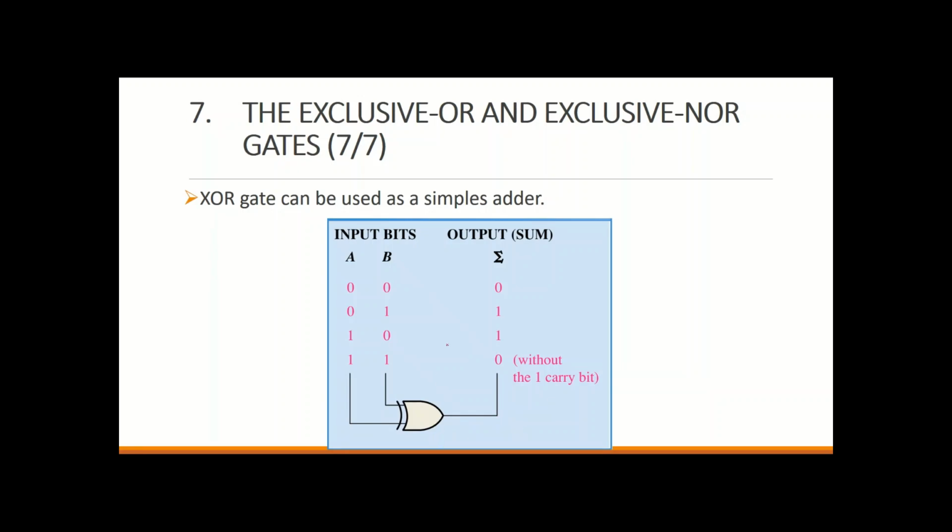All right. So this is another application for an XOR gate. The XOR gate can be used for logic addition, which is somehow the type of XOR. How do I know? Now look, 0 XOR 0 is 0, 0 XOR 1 is 1, 1 XOR 0 is 1. How do I know? The levels are not the same here. How about here? 1 plus 1 actually is 10. So we say the sum is 0 because the levels are the same, with 1 carried.